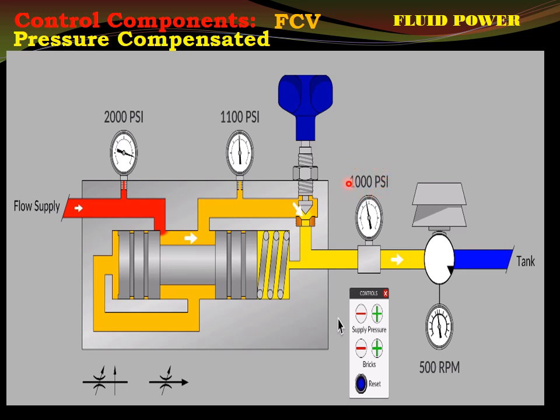It must increase, because I said earlier, more load demands more pressure. I explained with a linear actuator; in a rotary actuator, the same story. And since pressure increases here, definitely pressure here should also increase to keep the pressure difference constant, to keep flow through this constant, to keep rotational speed constant here.